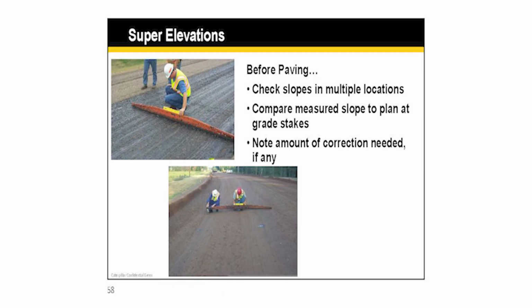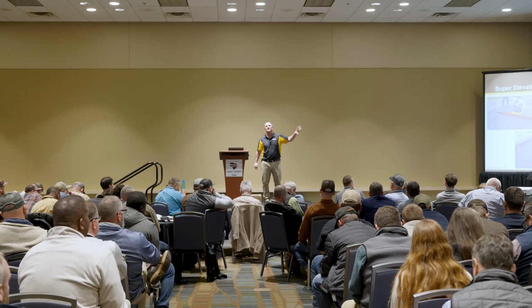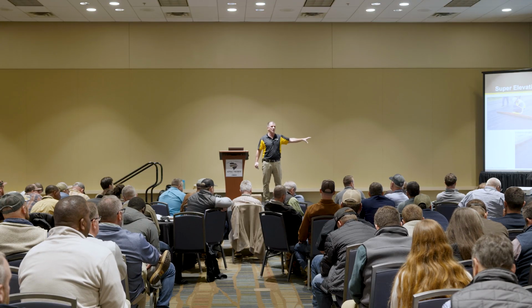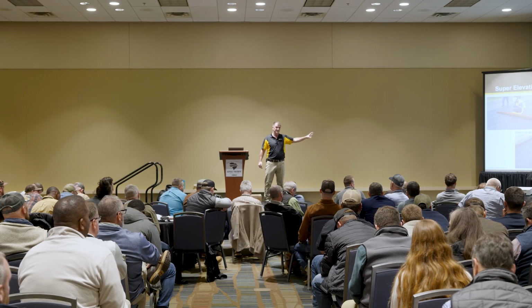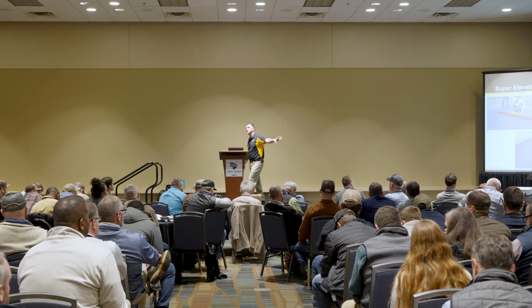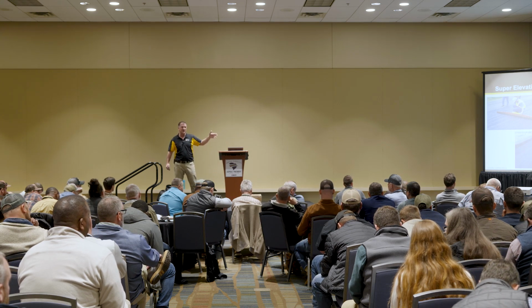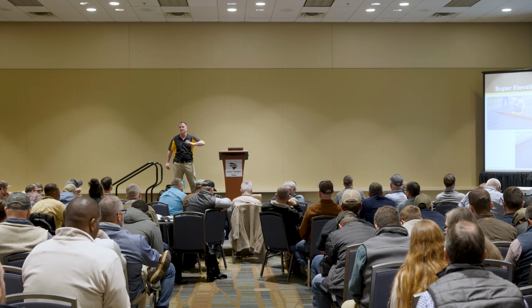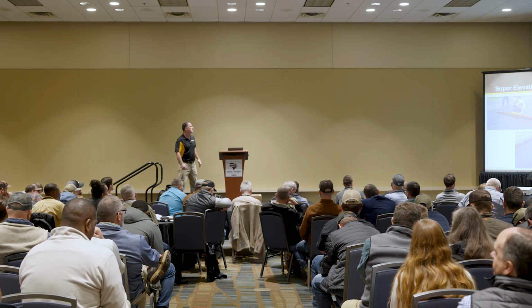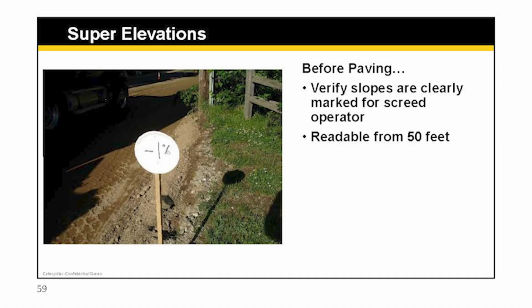Again, big thing here is checking ahead, whether it's milled or milled surface, aggregate base, and then making note of any corrections that are necessary to that base before we get in there. Or having that discussion that, hey, we're going to have to use some more mix here to correct or get this final profile right going through this super.